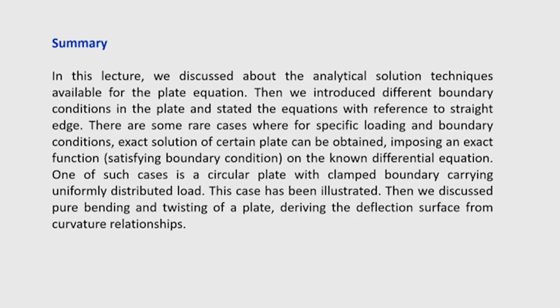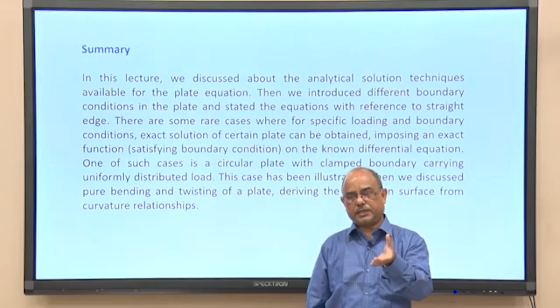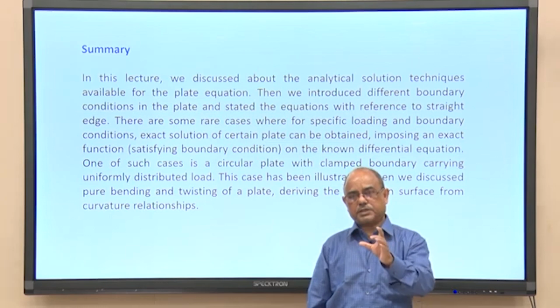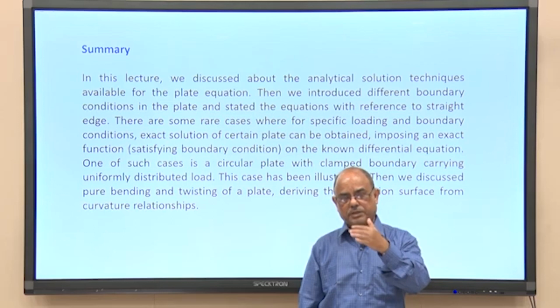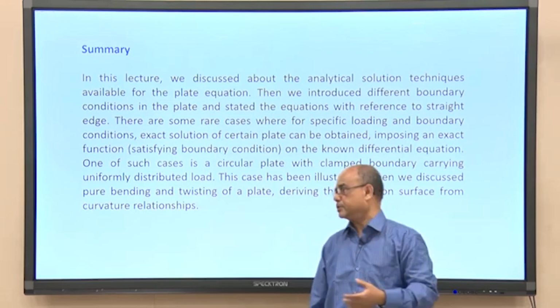As usual in case of beam also we have seen that deflection decreases if we increase the depth of the beam. Here also in the plate equation we have seen that deflection decreases when the thickness of the plate is increased, because in the flexural rigidity of the plate the h cube term is appearing. So, there is similarity between the beam and plate also.